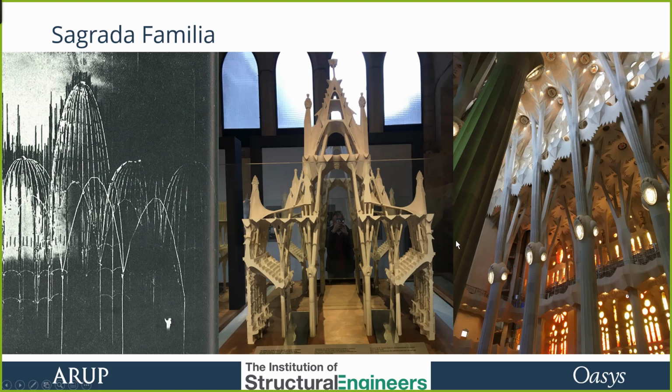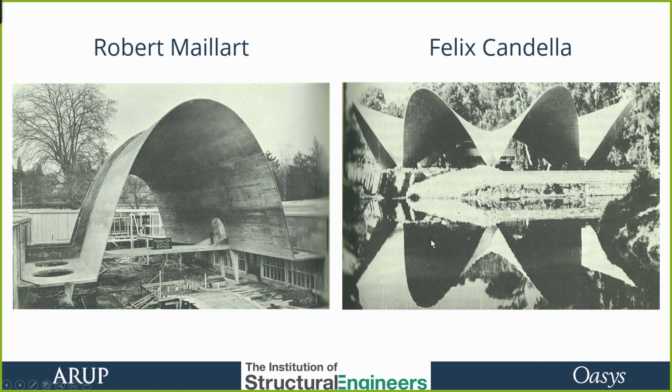Now these are actual catenary structures, but you can just go for parabolas. Parabolas are pretty close to catenaries, not quite exactly the same, but for concrete shell structures, they have some inherent stiffness of their own, and parabolas can be close enough. This is one example on the left, 1939. You can get an idea of how thin that shell is from the size of the person standing on the bridge. Now, parabolas have the additional advantage in that they are actually a double ruled surface.